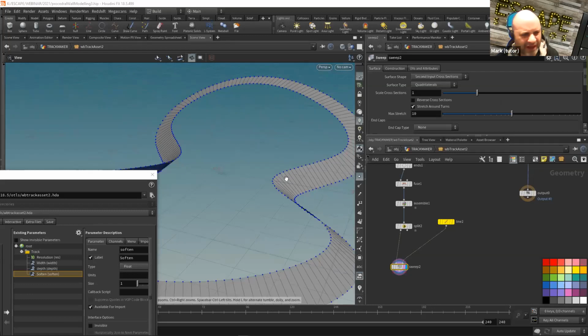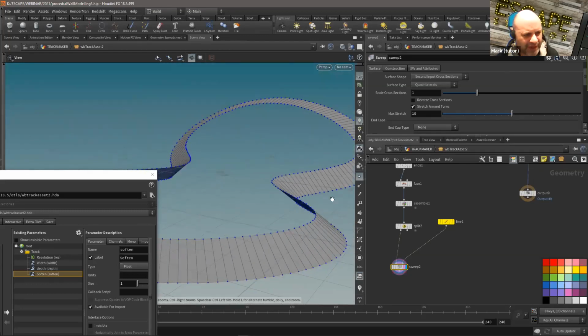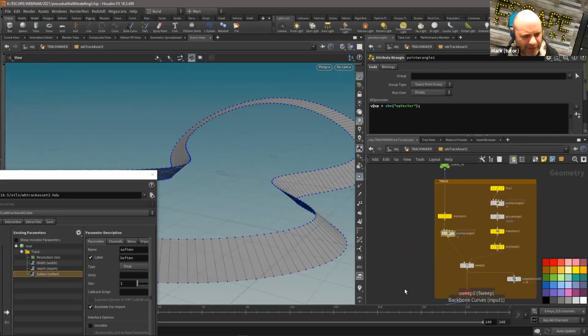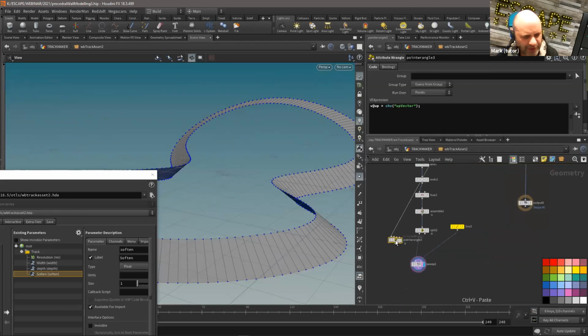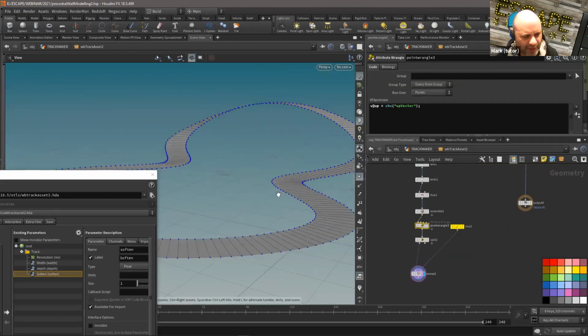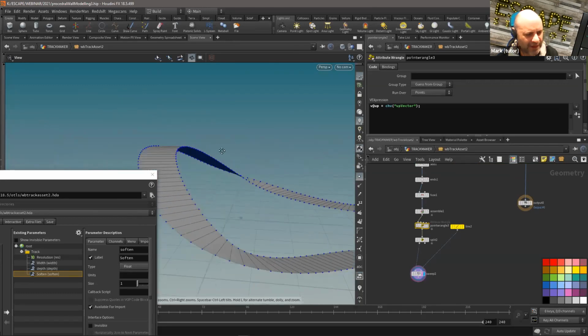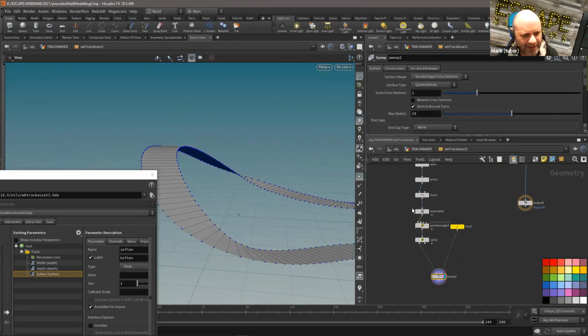So that's not really working as we expect because it's being rotated. Again, we need the up angle, so that up vector. So if you remember, I made this pointer angle up here. Let me just copy that one. And we'll just paste it up here so it gets copied into both curves. And there you can see that that's getting copied parallel to the floor again because we popped in our up vector.